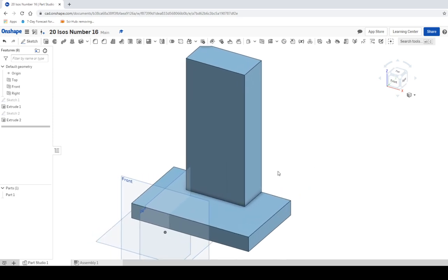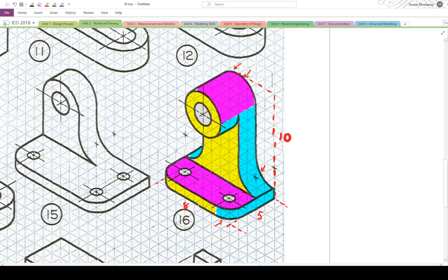Looking at the top view, we're going to use the fillet command this time to get these edges that are going around this way. Instead of thinking about it as a cut, think of it like a weld or an additive fillet, if you've got it between 2 corners like this, or it's making a corner on the inside. So we're going to go back here and say this fillet is 2 inches, and these fillets up here are also 2 inches.